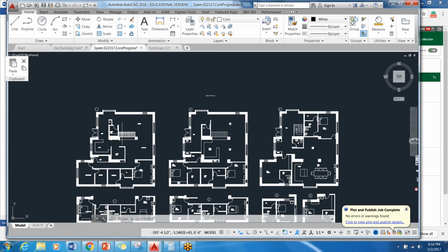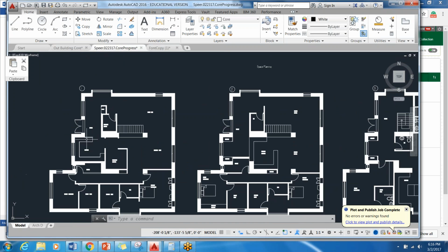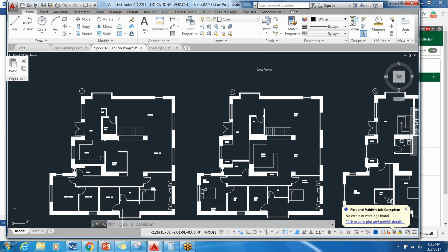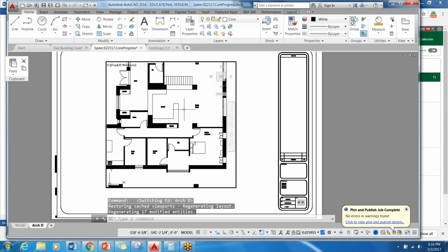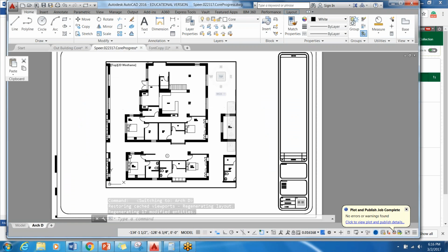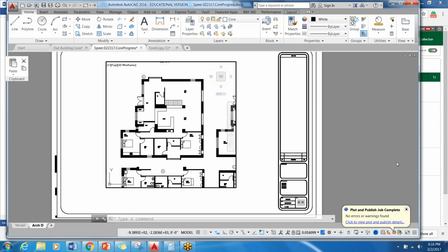So just the building without any furniture in it needs to have the text, whatever text you use, put on the actual architectural D sheet, and you have to scale it to be 1/4 of an inch, and then you have to start using your different text heights the way that I showed you to do the text heights today with annotative.